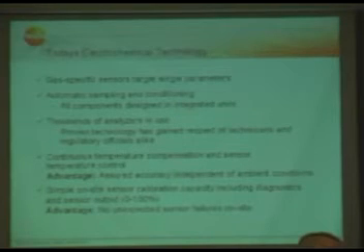It doesn't matter if there's a lot of humidity in the flue gas or if it's hot outside, because if you're just using a condensate trap without a gas preparation unit, in many applications it works, but you cannot really compare different applications together. Therefore the gas preparation makes sure that the flue gas is being dried, and then you can compare the readings.